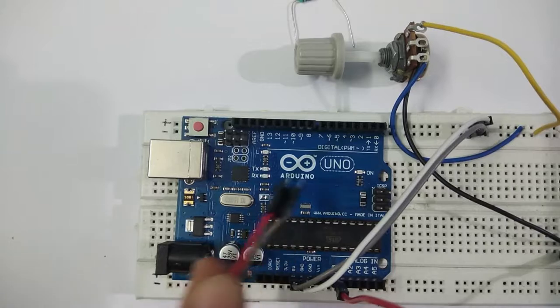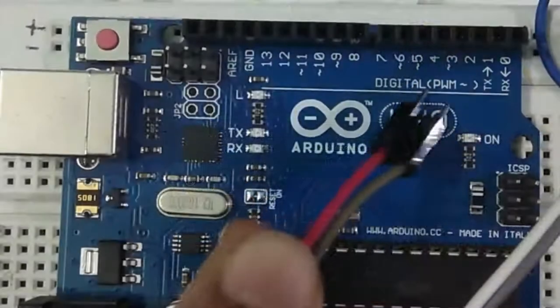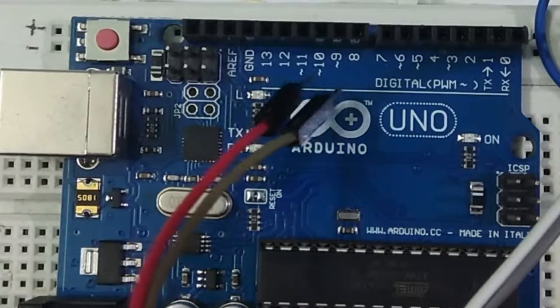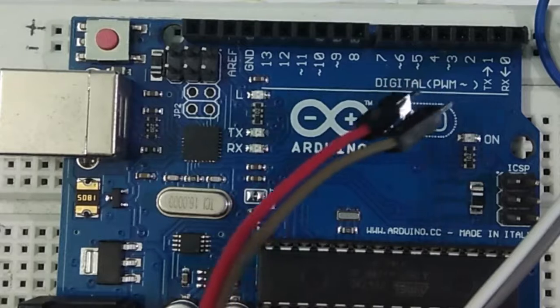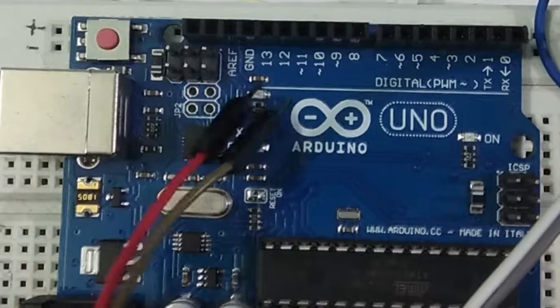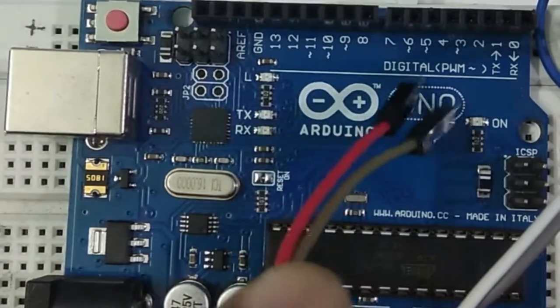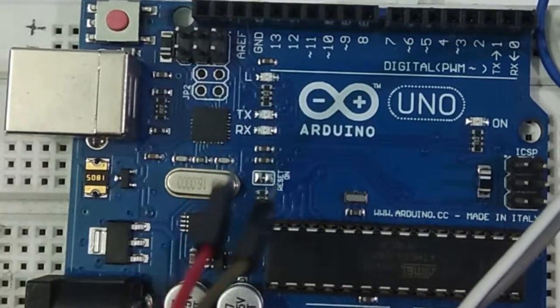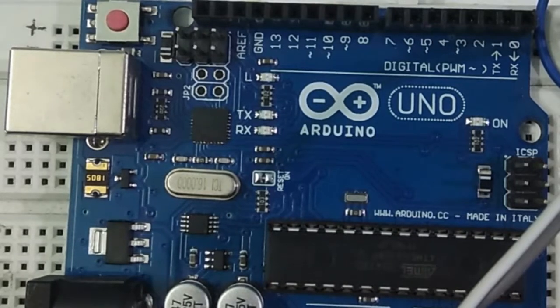See here, it is mentioned as digital PWM, digital pins, and PWM with the approximate symbol. 11, 10, 9, 6, 5, 3 are the pulse width modulation pins. If we give input from the other pins, these values do not respond. They respond as 0 or 5. But if we give input from the pulse width modulation pins, a varying signal, that means the intensity of the light or intensity of the signal is varied from 0 to 5 volt, 0, 1, 2, 3, 4, 5, likewise.